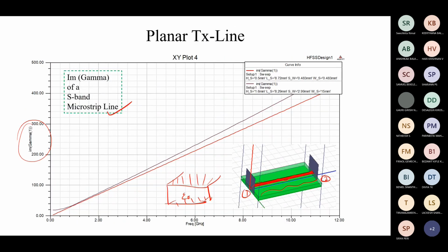So this is one important reason that even for frequencies like megahertz and gigahertz and up to tens of gigahertz, this PCB-based transmission line, or microstrip line, is one of the most successful ones. This is one of the important reasons you could see that this PCB structure is used for low frequency radios, like the FM radio. You can see that it is mostly made up of PCB-based structures.